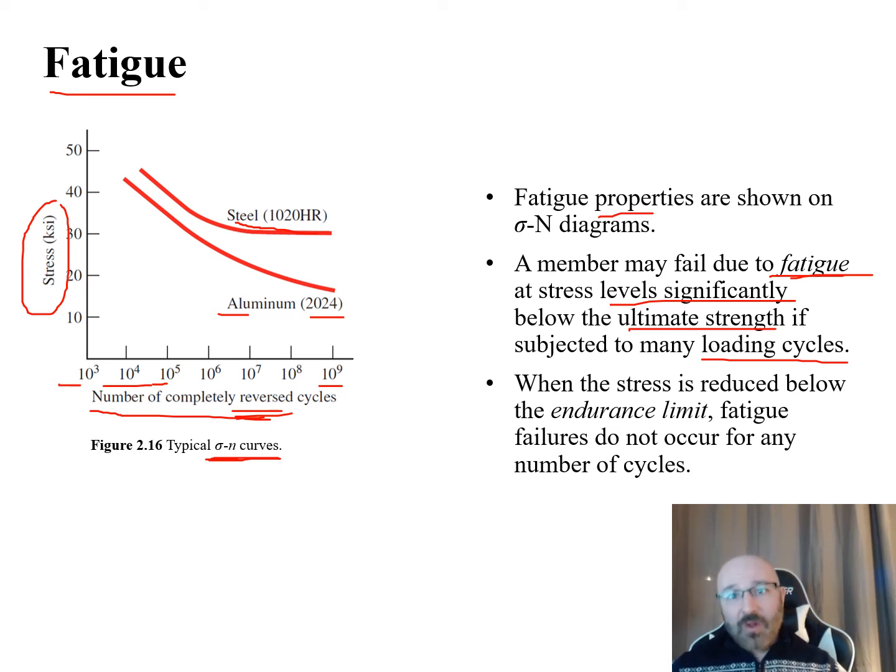And for how long? If we say it's going to be 600 times in a week, and we run 10,000, 20,000, 30,000 cycles and see when it fails, and we only take it up to that realistic 200-pound tension load, then we can put a life cycle limit on that. We can say this belt has been tested for an average lifter 6 days a week in the gym for 3 years before you're going to see any failure. So I can put a warranty on my buckles and lever shafts for that amount of time. This really does tie directly into your ME 171 course and future courses where you're talking about design work.